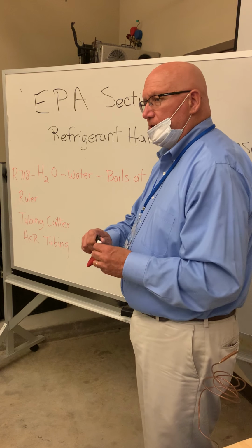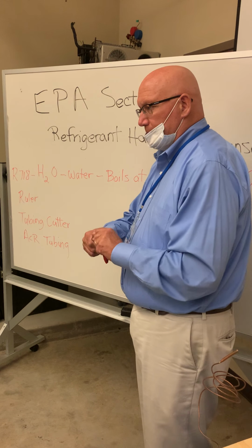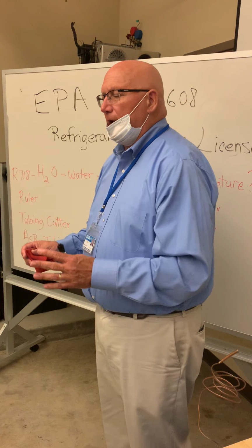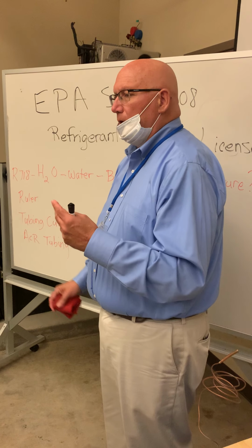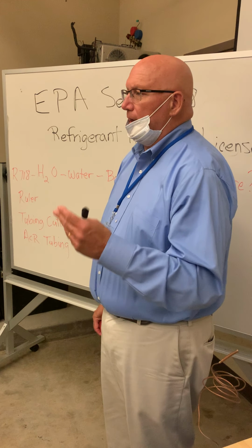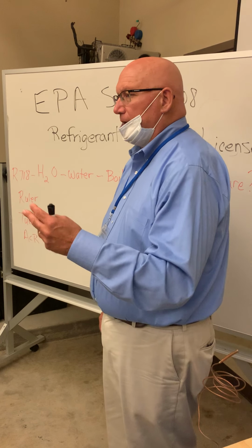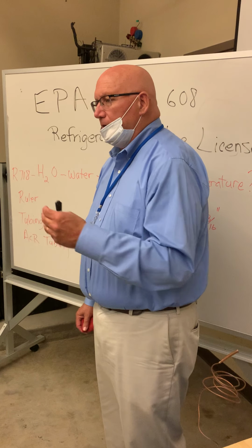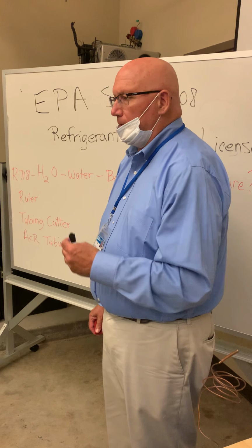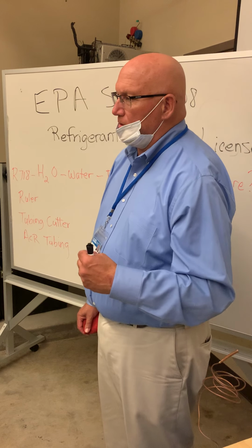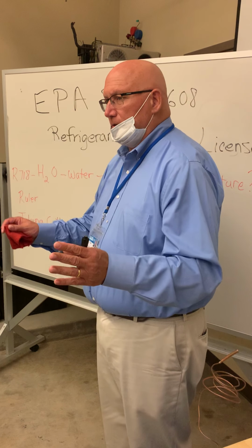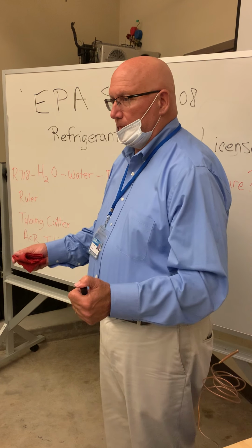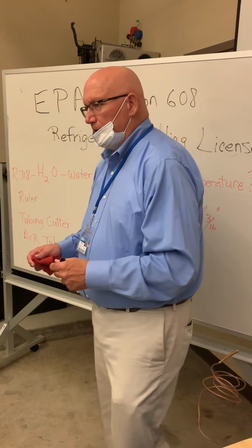It's 100 questions, all multiple choice. And none of it is about anything with electric. It's all about handling refrigerant. So they want to know that you know how to use a manifold gauge set. You know how to charge a system. That means add refrigerant into a system. That you know how to remove refrigerant from a system and store it in an external container without releasing it to the atmosphere. That's the point. So that's the license, and that's what they're going to teach you.